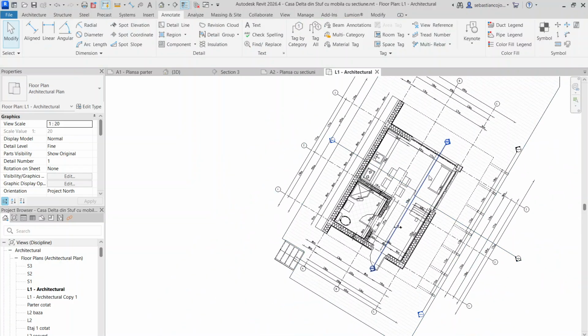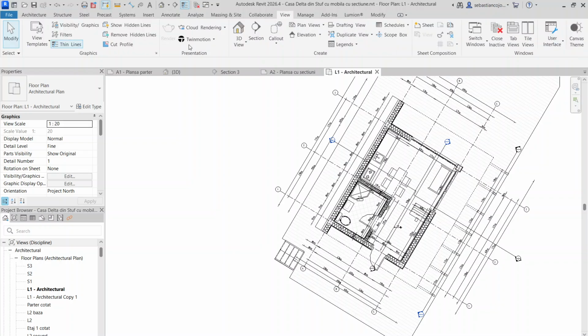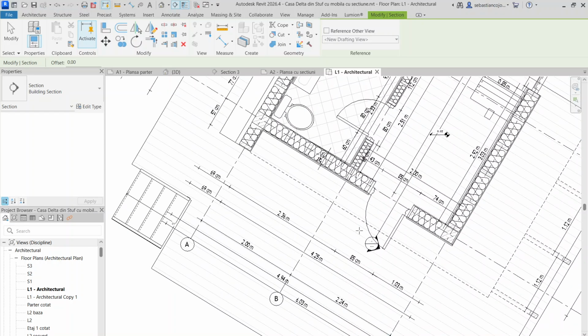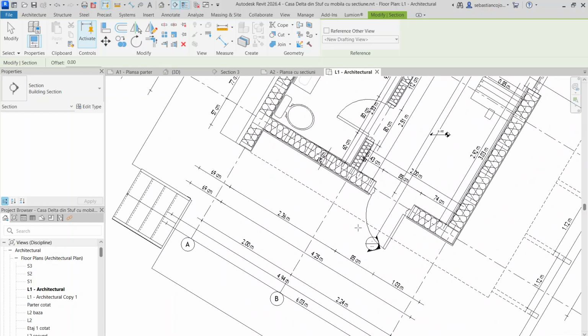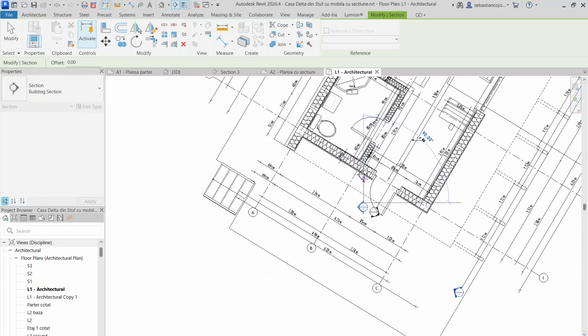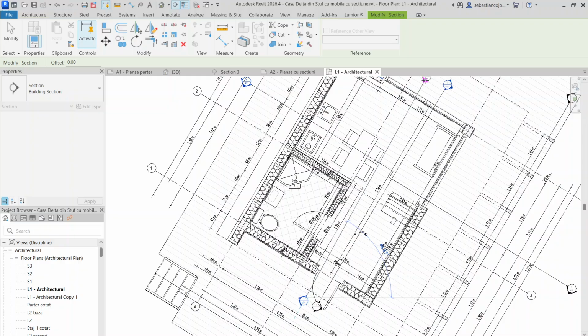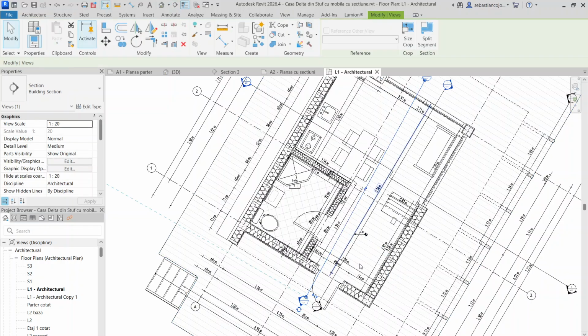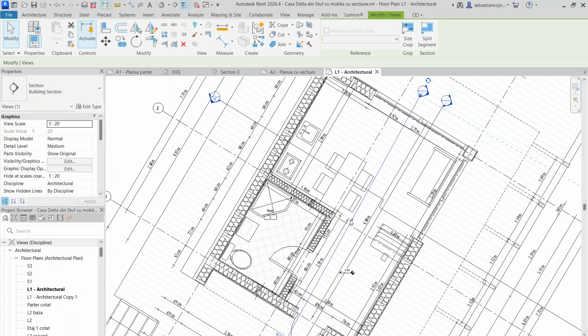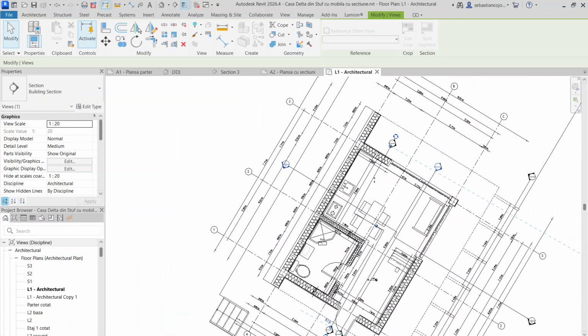And you also have the section lines, but you have view, section, and then you draw the section. But I already explained that in another video. I'll just summarize. So you have the starting point, and you maybe change the direction, have this arrow, and you can also split the line like this, or you can reunite it, and you can split a segment if you want to do an exact section.